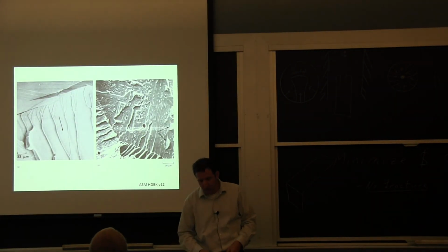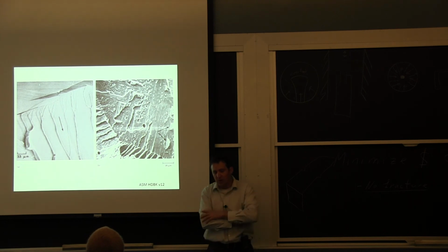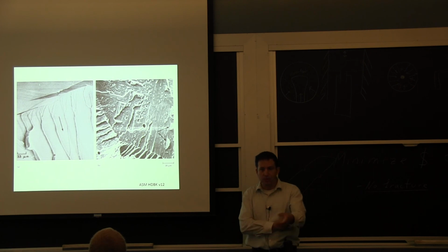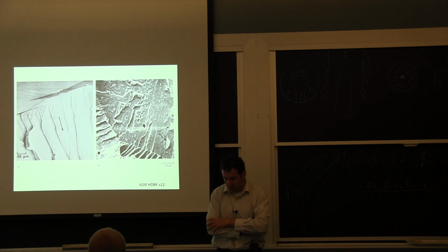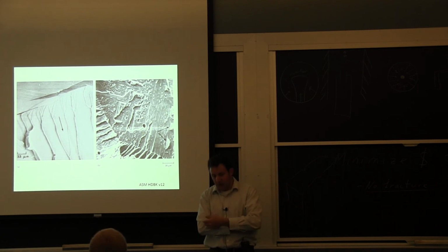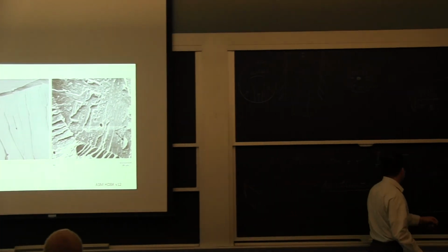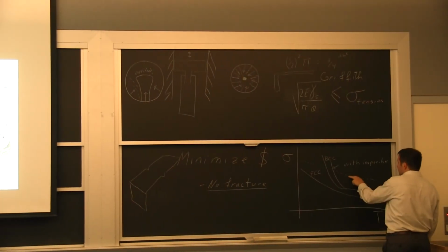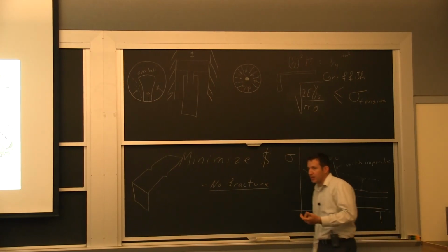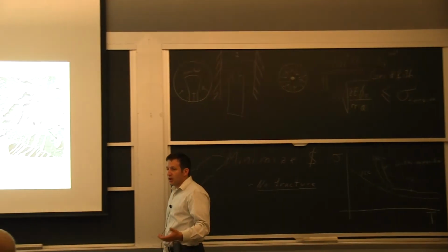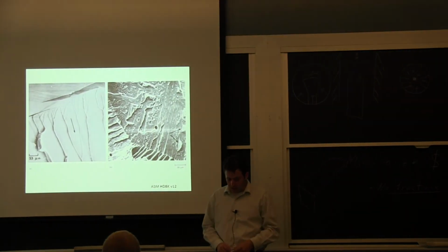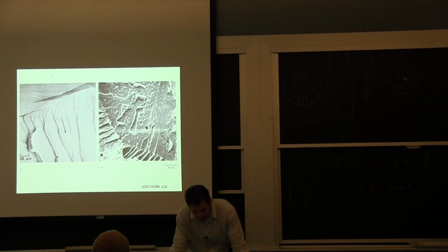So what I was going to finish with is just showing you a little bit what happens under the microscope. If you take any piece, including the two that I circulated, and you go at high magnification enough, you're going to be able to say how the breaking happened. So we're more interested now in this curve here when we're really reaching the capacity. If we are at low temperature, we can have cleavage, and that's what I'm showing here in this image.